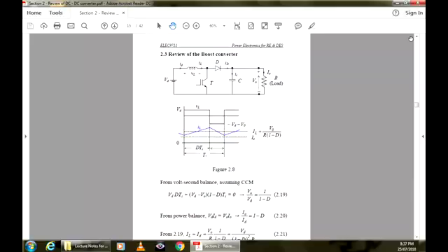Now, again we assume that this voltage V0 is larger than Vd, and it is constant because the DC capacitor current is 0. The DC current through the capacitor is 0. In order to have a constant rate of power flow, the current here would be DC, which means that if the current rose by a certain extent, it must fall by the same extent when the switch is off. The current rose by this extent when the switch was on.